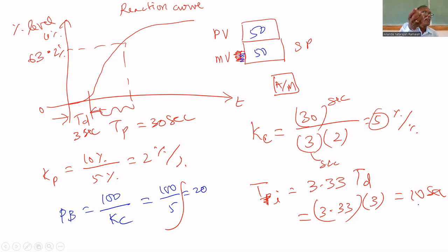After 3 hours, let us assume that some voltage is decreasing. What will happen to the flow rate? It will decrease. That's why the valve will open more to adjust the flow rate, so that again it will come to the 50% level. Do you understand that? That type of response is called regulatory response. Note down this value.